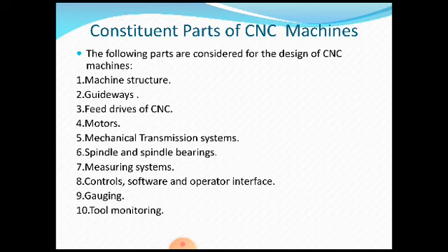Whenever we speak about the feed drives, these drives are responsible for giving the movements to the cutting tools. And the motors you are going to see here are special types of motors like servo and stepper motors, which are basically used in CNC machines, unlike regular motors like induction motors. These motors are specially designed, because the accuracy of the movement of these motors decides the production quality.